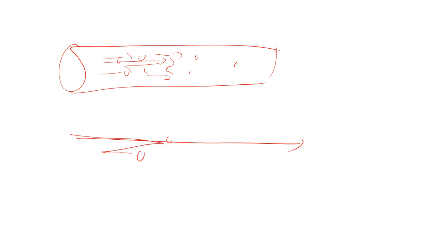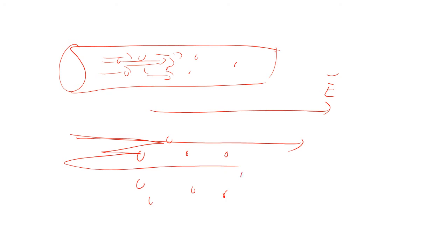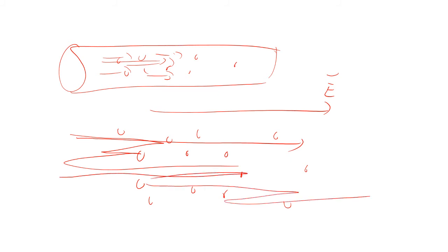When electric current goes through something, it also impacts the object it's going through. If electric charges are moving through here, they're bumping off of the atoms that are already in there. The charges don't really just go straight through because there are atoms in the way. So you get an electric field this way to the right, and the electrons bounce off of the atoms. The recoil of bouncing off causes that atom to move and vibrate. The more the atoms vibrate, the hotter the conductor gets. So you actually have heat generated with current flowing through something.